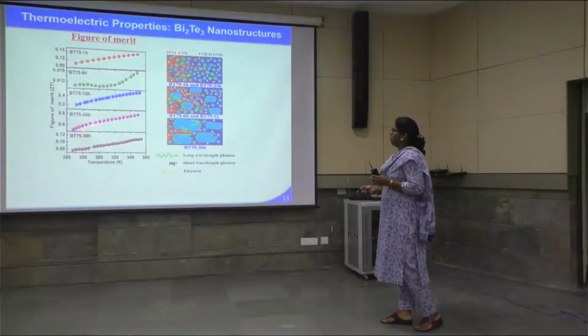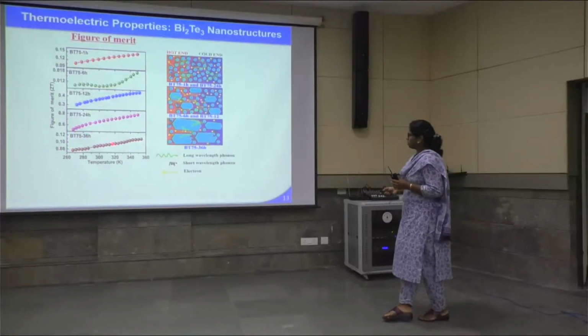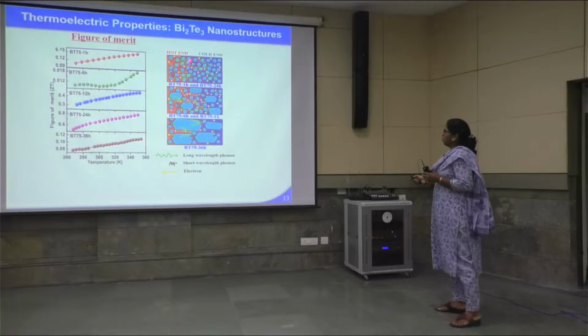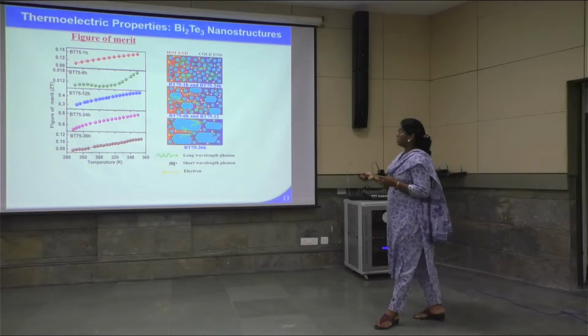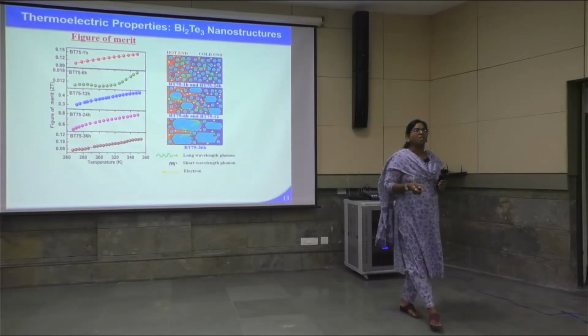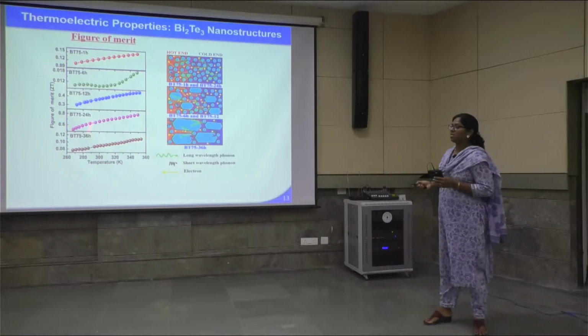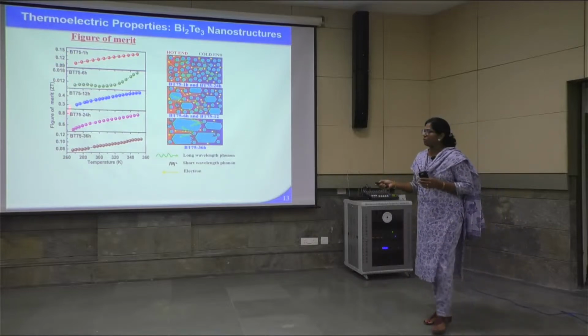This is the result of why the thermoelectric figure of merit values have become higher. Because what happened here is that the long wavelength phonons are very few here, and that has helped. Out of three parameters, the thermal conductivity played a major role here. Because of the higher thermal conductivity values in these two types of morphology,